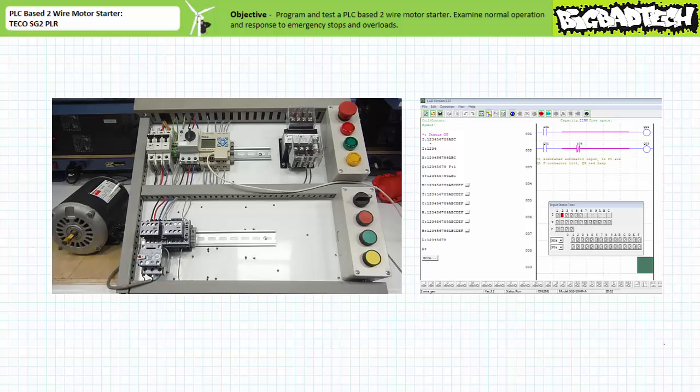As can be expected, when the selector switch on input 1 is open, the F contactor coil is not energized and the motor is off. Output Q1 is not asserted and the F1 auxiliary contact indicates that the F contactor is open and the red pilot lamp is off. When the selector switch on input 1 is closed, the F contactor coil is energized, the F primary contacts close, and the motor turns on.